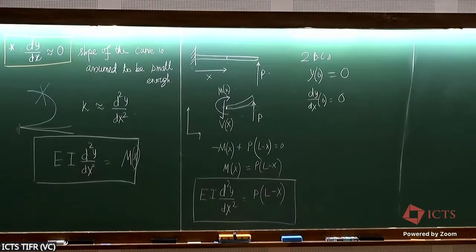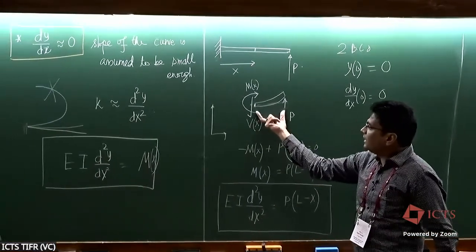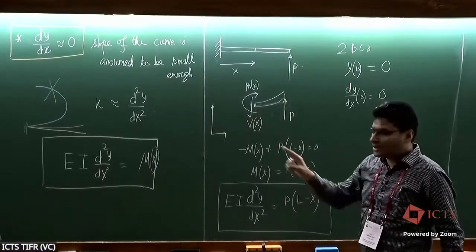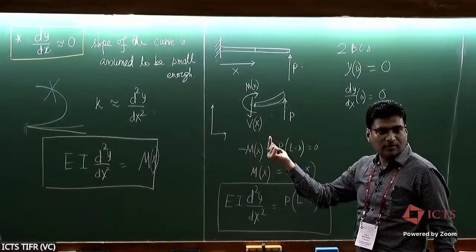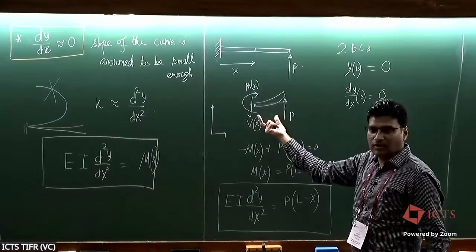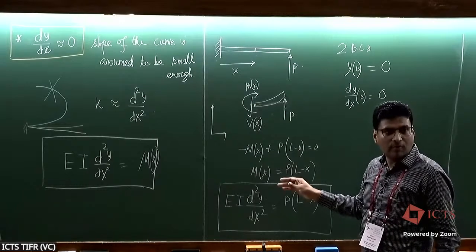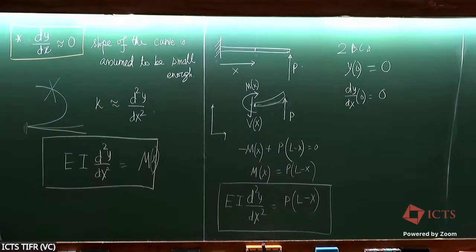Yeah, in the actual rod theory later on, you will have a differential equation for the moment. Here you don't need that, because although this length is not the same as L minus x, in Euler-Bernoulli beam theory we are saying that the axial deflection is negligible. So we are making it L minus x, and then it gets completely determined. For Euler-Bernoulli beam theory purposes, you don't need any extra equation. This is good enough.